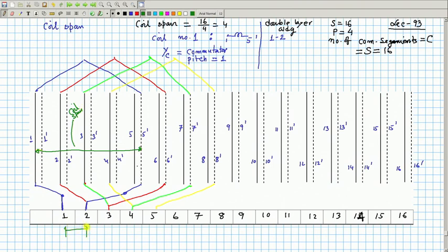This is coil Y c, commutator pitch, which is plus 1. They say plus minus 1. You could also terminate it to this terminal, winding will be happily progressing, no point, but let us restrict the discussion to 1.